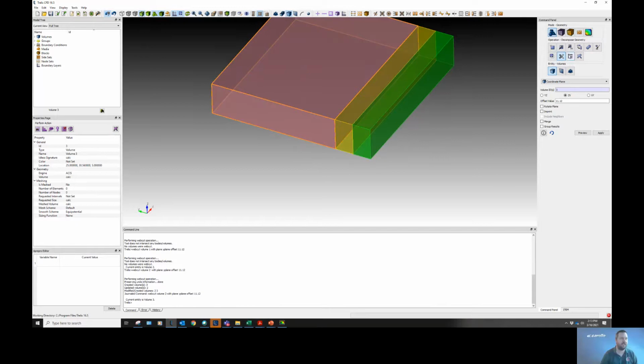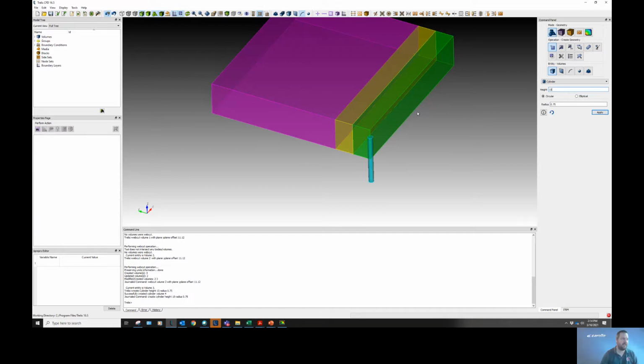We also need to create our inlet. And again, there's a couple ways to do this. We could create a cylinder that is 18 inches in diameter, so the radius would be 0.75 feet. And in this software, you don't get a lot of options on where to start. If we want it 10 diameters long, that would be 15 feet. And so we create it, and it creates it at the centroid again. So we could move it.